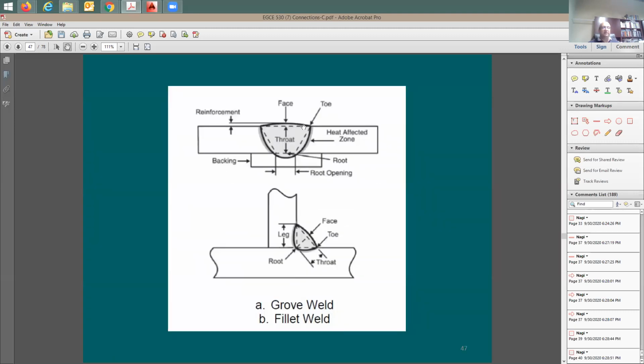So what you're doing here is full welding, and they call this butt welding. This is going to be full penetration, because you're interrupting the entire plate and the welding material is going to be here. In order for you to do this, you need to put a backing plate. This backing plate is not part of the weld, and later on you can knock it off.